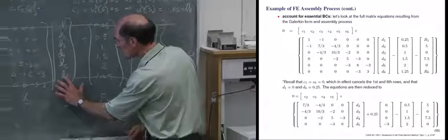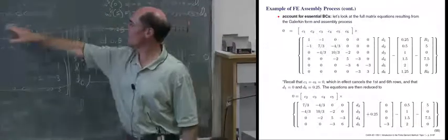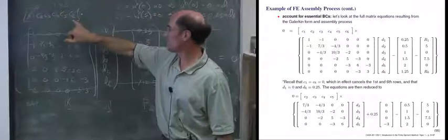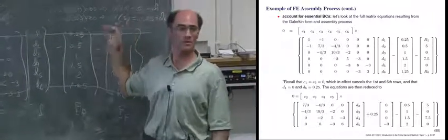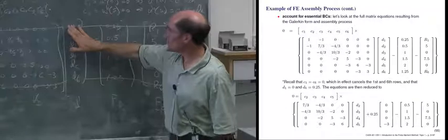So the question, I should repeat for the recording, was why is C1 equal to 0, or also C6? It's because these are the nodal values of the weighting function, and the weighting function is 0 where we have a prescribed displacement. That's the reason.